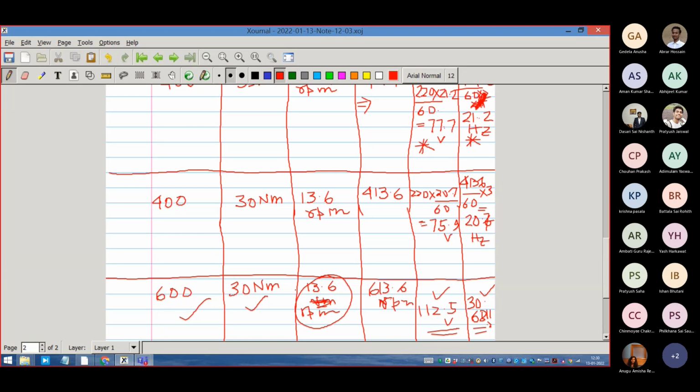Now you obviously understand that here, in order to determine the right amount of S omega s, we need the torque information, which is not available externally, which is not available to the drive system. So the drive has to do what? It has to do a search method, a kind of trial and error method. Trial and error method means what? It will, let us say, arbitrarily choose 15 RPM. Suppose in this case, it will first choose 15 RPM.